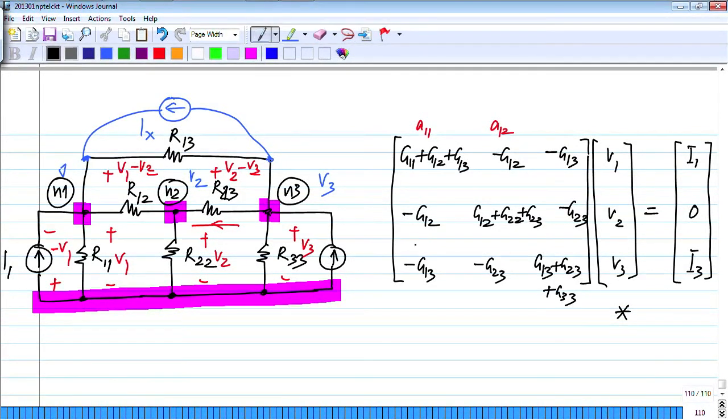Okay. That is, please answer the question in terms of what will change. Is it, first of all, the right hand side that's going to change or the left hand side? Yeah, I think it's pretty clear because we've added an independent current source that has to appear on the right hand side. So the right hand side will change. Okay, this will influence the right hand side.